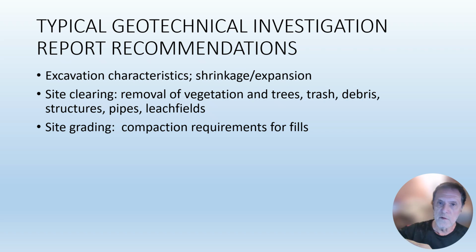You can look at a hillside, you can cut on the high side and take that material that's cut away and put it on the low side of the hill so that you have a flat pad. That leaves you with a cut slope on the higher uphill side and a fill slope on the downslope side. The fill slope is composed of fill, and the pad may be composed of fill as well. You're going to set your building on top of that filled pad.